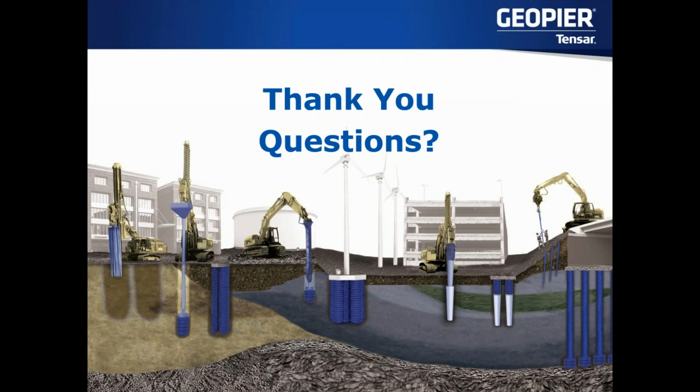The only requirement we would have to do is whether or not whatever agency is reviewing our work would require it. And unfortunately, Chicago is one of those places that started requiring multiple full-scale footing load tests on jobs. And the reality is it just doesn't add value to a project. I mentioned the group effect of measuring the response of multiple piers. That's fun, it's interesting to see how things respond, but in my opinion, the cost just doesn't justify the means to do it.